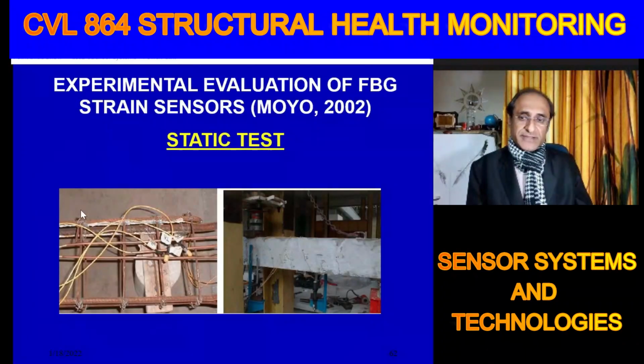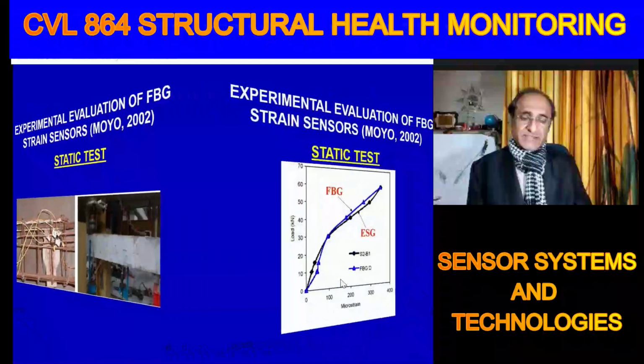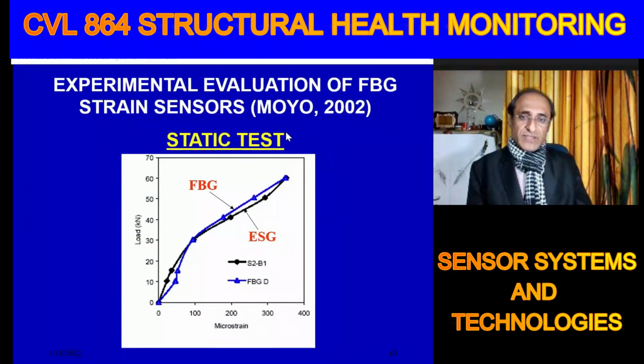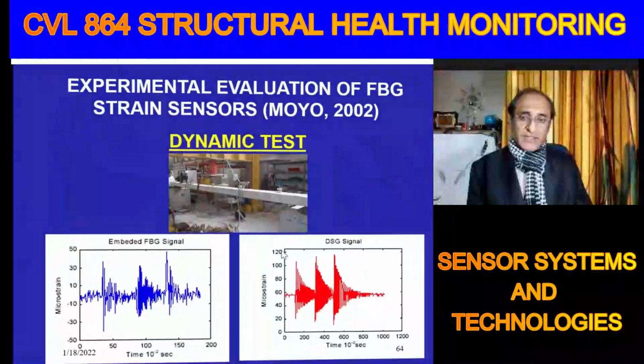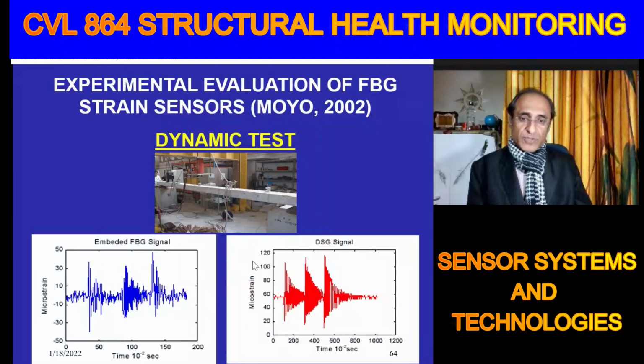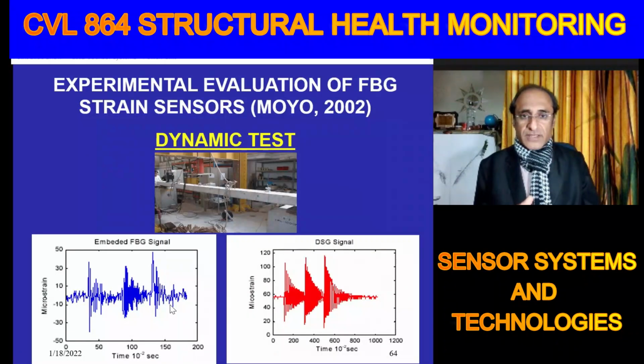And here these are shown installed inside concrete and attached to the rebars, for static tests. And this is one of the early tests in the field of the FBG sensors. And then this is a dynamic test, a comparison between an accelerometer and these fiber optic sensors.